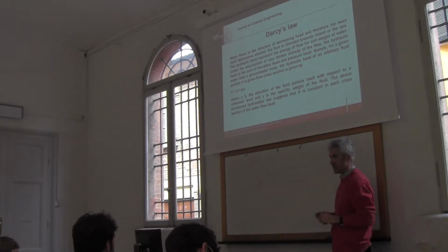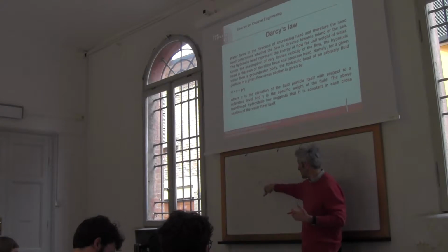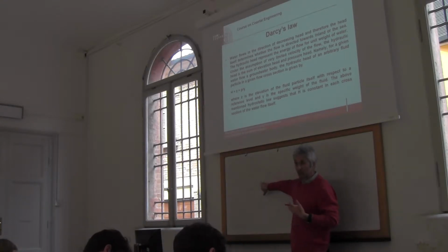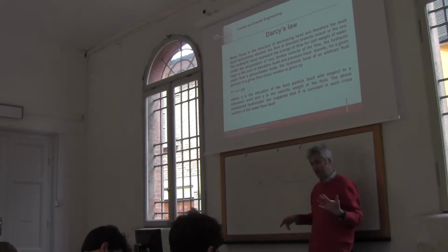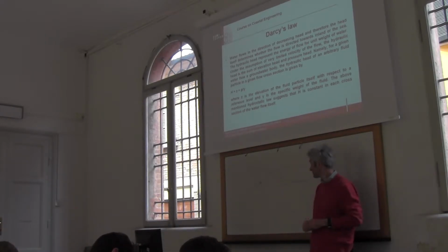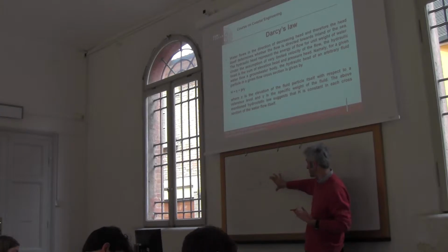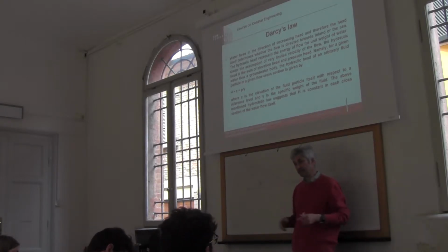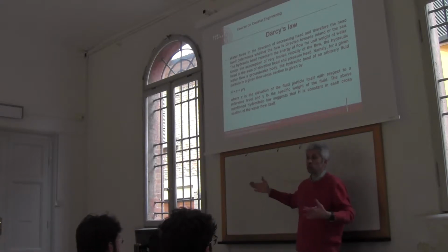With the symbol H, the difference in altitude between mean sea level and the interface, and this is what I am interested to estimate. If I want to locate the position of the interface, I need to estimate its position relatively to the mean seawater level, for instance.